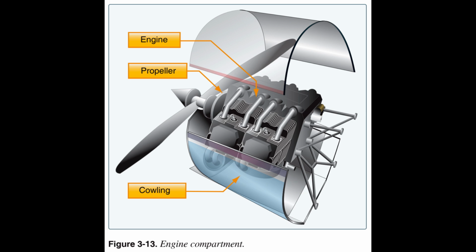There are 2 significant factors involved in the design of a propeller that impact its effectiveness. The angle of a propeller blade, as measured against the hub of the propeller, keeps the angle of attack, AOA (see definition in glossary), relatively constant along the span of the propeller blade, reducing or eliminating the possibility of a stall.